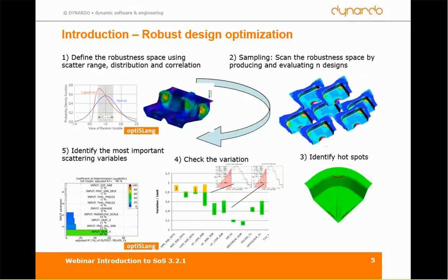But, as already announced, there is an easier and less error-prone workflow available using discrete random fields and Statistics on Structures. With SoS, one does not need to identify any a priori one-dimensional or three-dimensional point. We take the uncertainties on the input side, which might be already well-defined random variables, building a robust sampling and evaluating finite element solutions of discrete measurements afterwards using SoS. Only in this manner one might be sure to get reliable hotspot information.